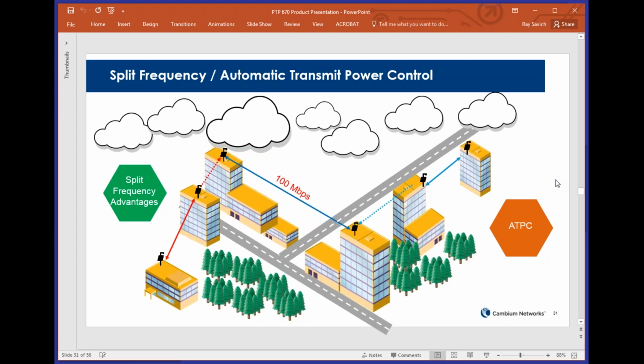The next best solution that we have is splitting up the TX and RX frequencies. In this case, we would use the TX for blue, which means you're going to transmit from the blue and then receive from the red. Because you're receiving on the red, even though you're going to receive channel interference from the blue from the other radios, it's not going to affect the radio, because you're not on the same frequency or band. You're just slightly different. So you're able to still achieve the 400 Mbps link that you have, while also keeping track of all these obscurities that happen in the real world.